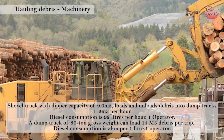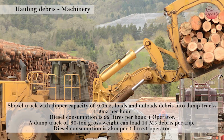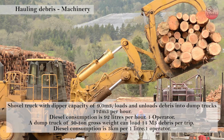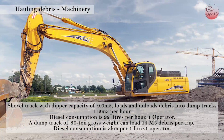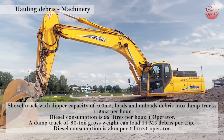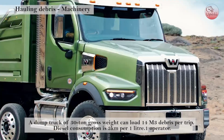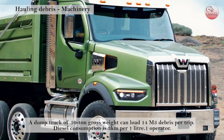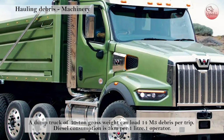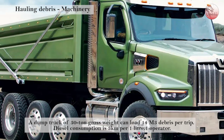Hauling debris machinery: shovel truck with dipper capacity of 9 cubic meters loads and unloads debris into dump truck at 112 cubic meters per hour. Diesel consumption is 92 liters per hour. 1 operator. Dump truck of 30 ton gross weight can load 14 cubic meters of debris per trip. Diesel consumption is 3 km per 1 liter.